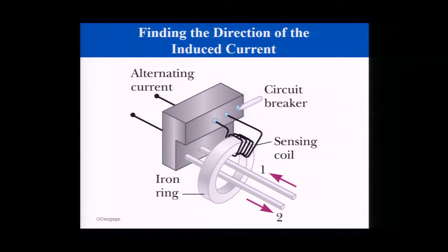What's kind of cool is we can use this to our advantage. So circuit breakers are doing this. So if I've got a current and all of a sudden I sense I have a current, I've got a little magnet in here, and if the current exceeds a certain point, it's going to cause enough repulsion that trips the breaker, and we see the switch flip.